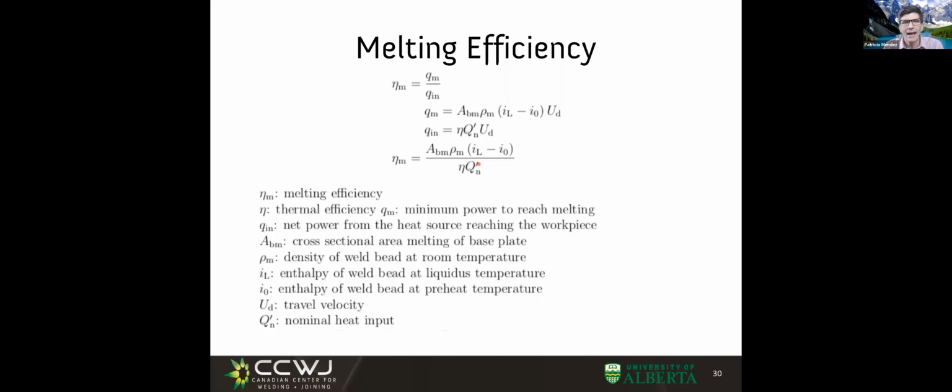So if I have high heat input, but I melted little, that means I'm going to address the first question. Yes, high melting efficiency and low nominal heat input is what we want, because the high heat input, whatever I didn't melt, goes out in the form of thermal expansion that will create more distortion. So for a given weld, I want to use as little heat input as I can. So high heat input is typically not our friend.